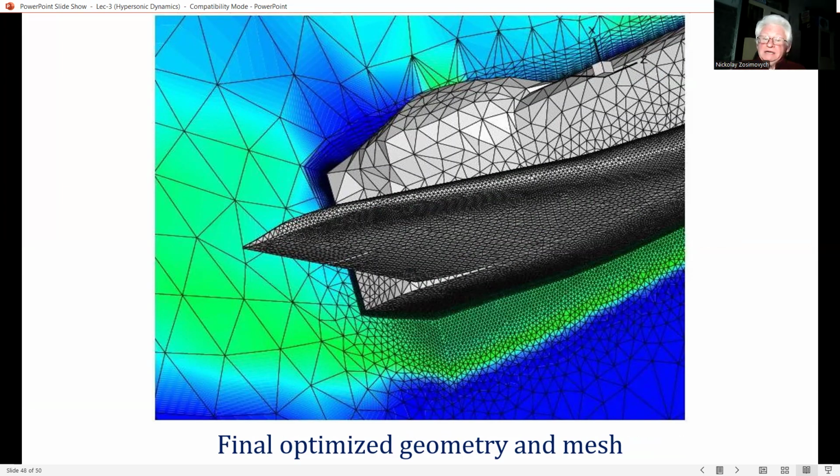An angle of attack of 20 degrees was chosen because the baseline HL-20 has a maximum value of lift-to-drag ratio of 1.50 at this angle of attack.